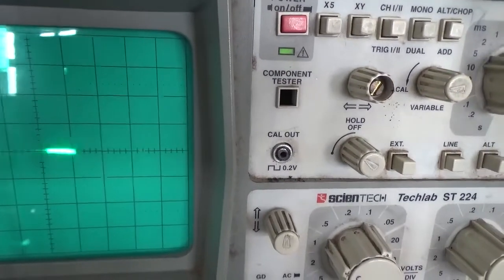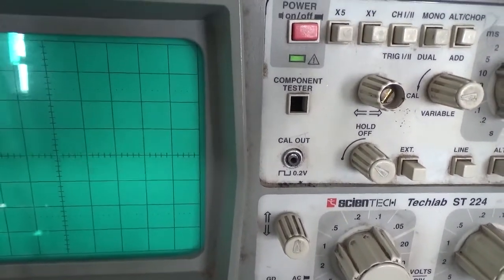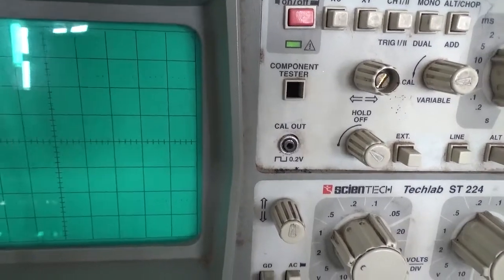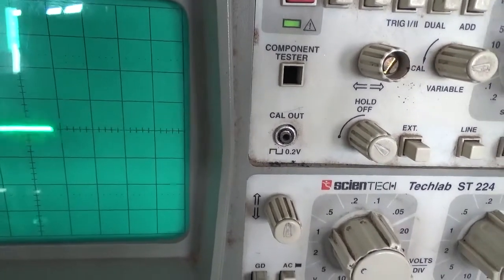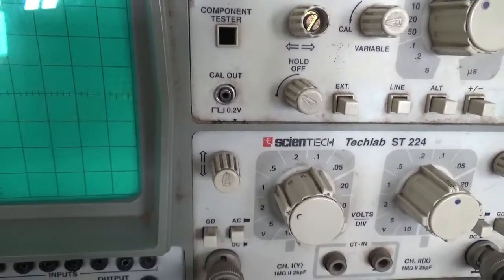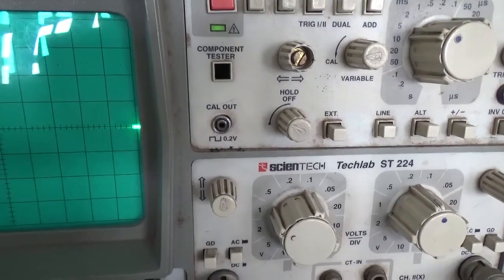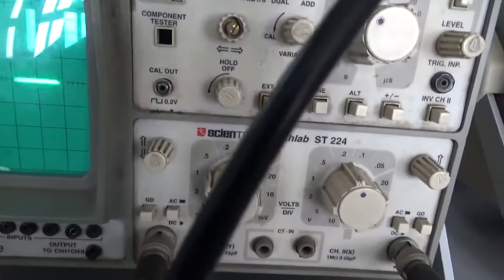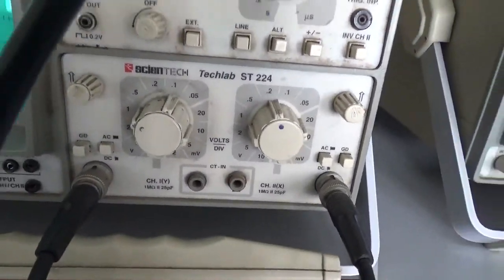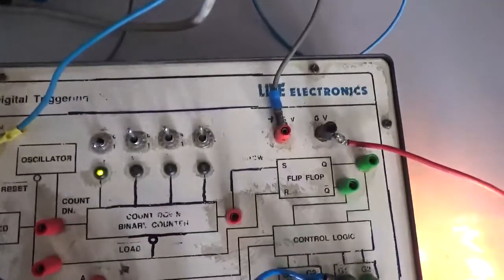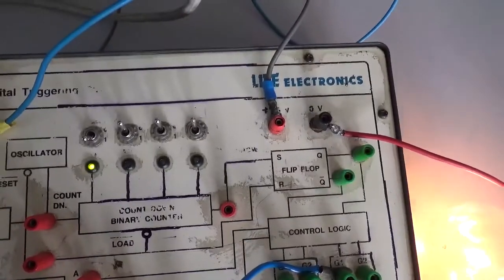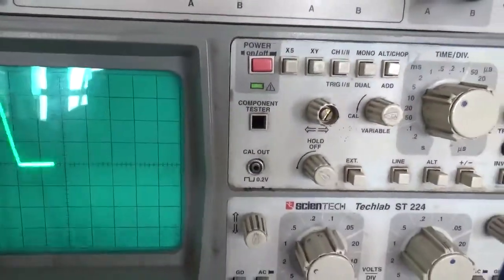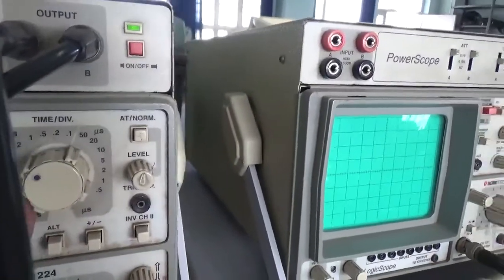Alpha 90 degrees. Then I am further increasing the digital data to 12, 14, and then when you go for 15, very minimum RMS or DC voltage is expected at the output here. Now to measure the firing angle, let me take one of the cases where I kept the digital data as 1000, nothing but we can expect 90 degree alpha. So physically we can measure alpha is 90 degrees, or otherwise we set the time division to 5 milliseconds.